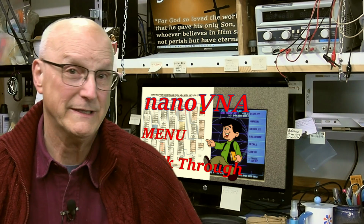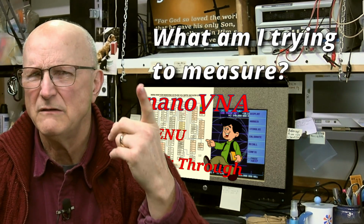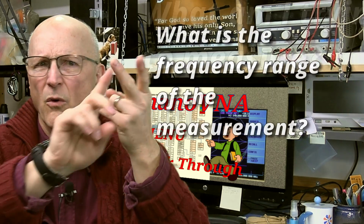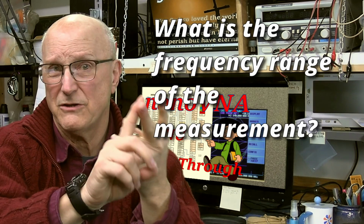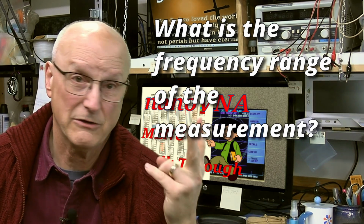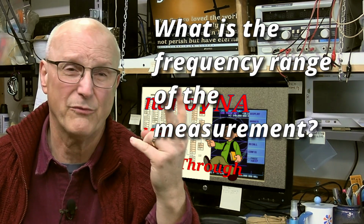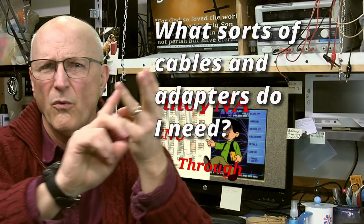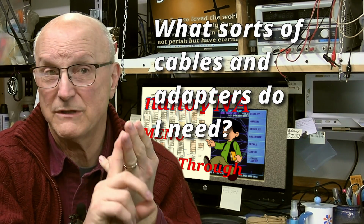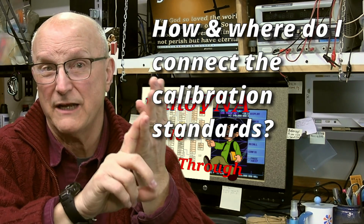With the nanoVNA, we want to ask questions like, what am I trying to measure? Am I trying to measure SWR, impedance, insertion loss, gain? What is the frequency range that I want to measure this in? Am I interested in a particular range of frequencies, such as the extent of a particular frequency band? Am I interested in a specific frequency and a range of frequencies around that specific frequency? What sorts of cables and or adapters am I going to need to interface with the thing I'm testing? And how and where am I going to connect my calibration standards?